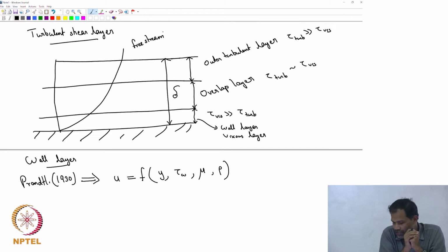It is basically going to be the sum of both, tau w. The stress is basically the force that you need to apply to maintain the flow. So this analysis already tells you that when you talk about just tau w, we will be able to talk about only a viscous contribution to that, because tau turbulent will be much smaller there.